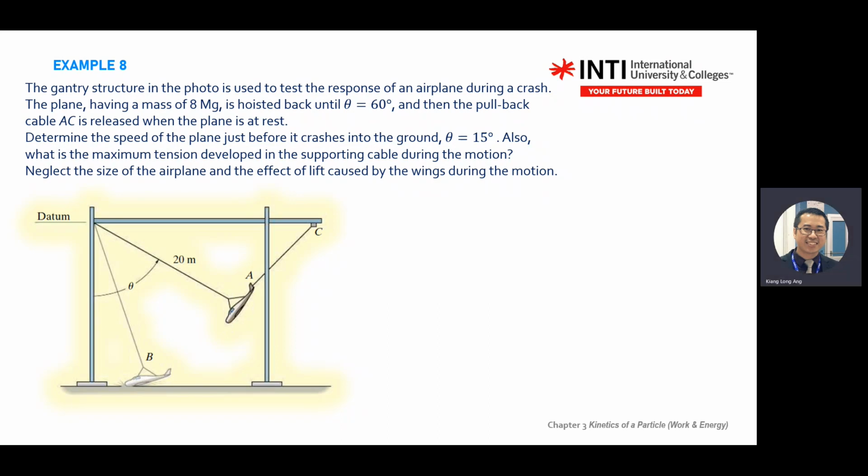So curvature motion, what do you bring? First, you always draw the free body diagram. Once you have the free body diagram with curvature motion, what do you put inside? Tangent and normal. Let's say this object, tangent, normal. What's the next step? Recall, you have normal direction and tangent direction. What's the equation for acceleration in normal? Tangent is a_t, which is v dot, the dv over dt. Normal is v squared over rho. Normal always deals with rho. So remember this way.